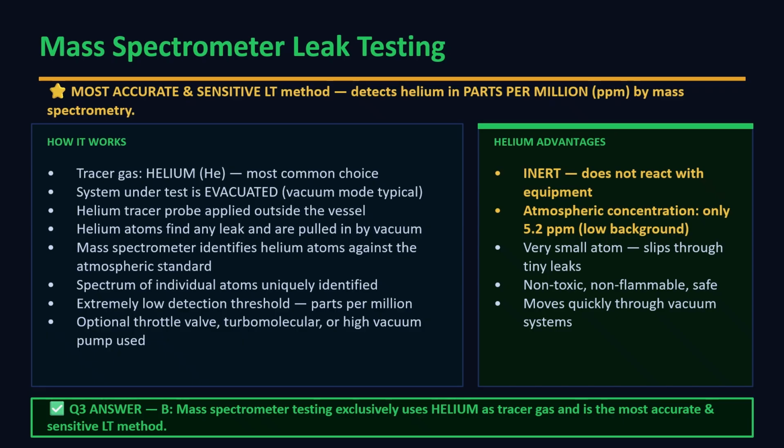Why helium? This question appears frequently in exams. Helium is inert, non-toxic, non-flammable, small atomic size, low atmospheric concentration. All of these characteristics make helium ideal for leak testing.